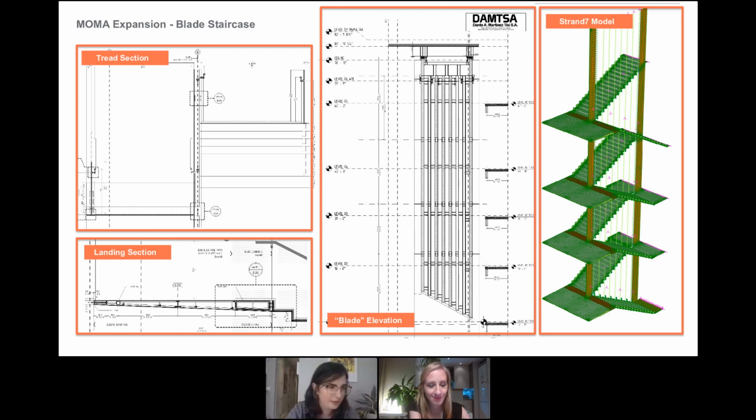And I think maximizing stiffness, minimizing mass is generally where you want to go. The higher the frequency, the better. Yeah, just to make sure that you don't start to excite it. Make sure it's thoroughly over that threshold.